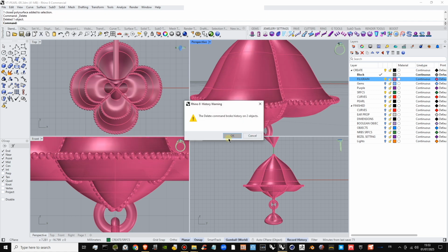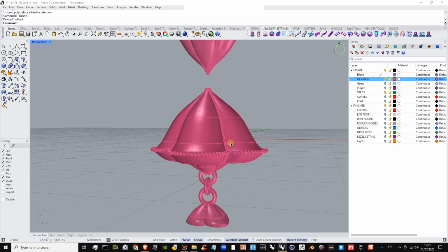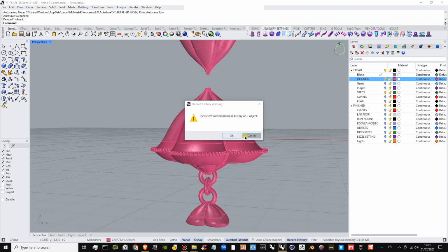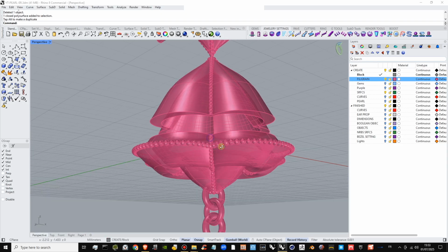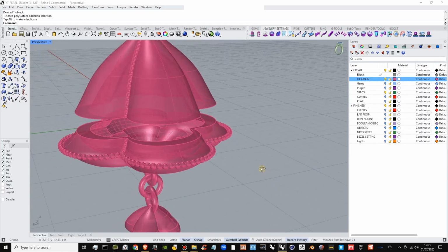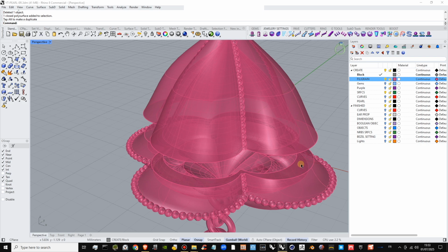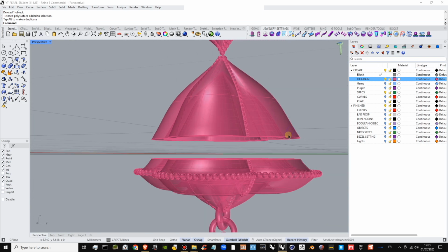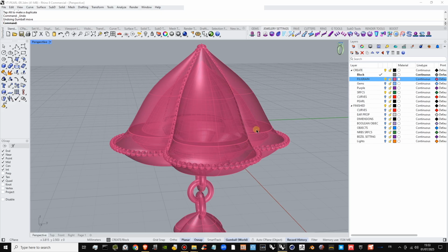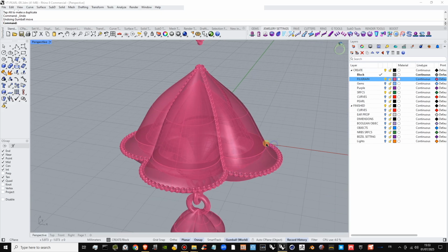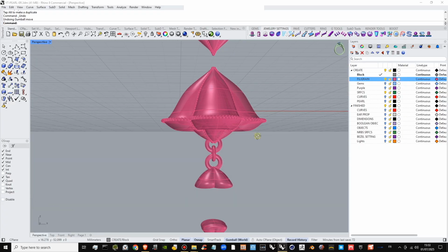And now we can delete the input, delete the originals. What we have left is two shells, a top and a bottom, that we can cast separately. What works really well is if you put some pins or just spheres that you hollow out on, you boolean on one side and is protruding on the other, and you can do a nice laser boolean with that, or you can create a step so that it sits even more carefully within that step. So that's one way you could hollow that piece out.